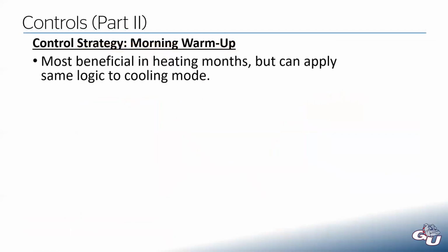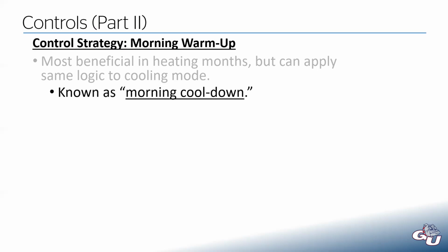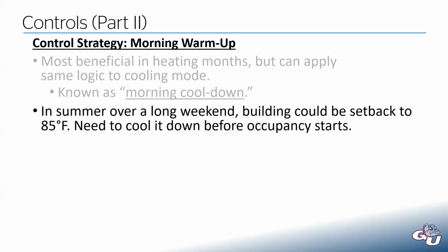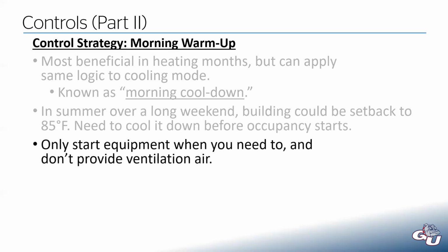Morning warm-up is the most beneficial in those heating months. It's not as beneficial in the cooling months, but we can apply it in those cooling mode days as well. So that would be morning cool down as opposed to morning warm-up. If we're in the summer and we have a long weekend, we could set our building back to 85 degrees. So we're raising the temperature of the building, and then we need to cool it down before occupancy starts. But we do the same thing. We only start the equipment when we need to, and we don't provide that ventilation air.